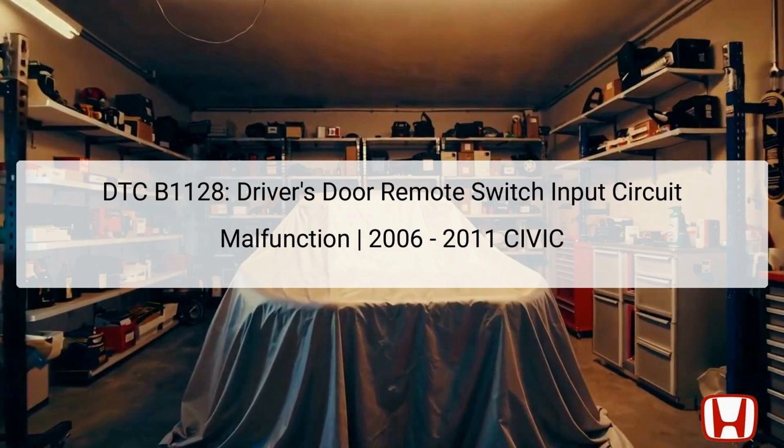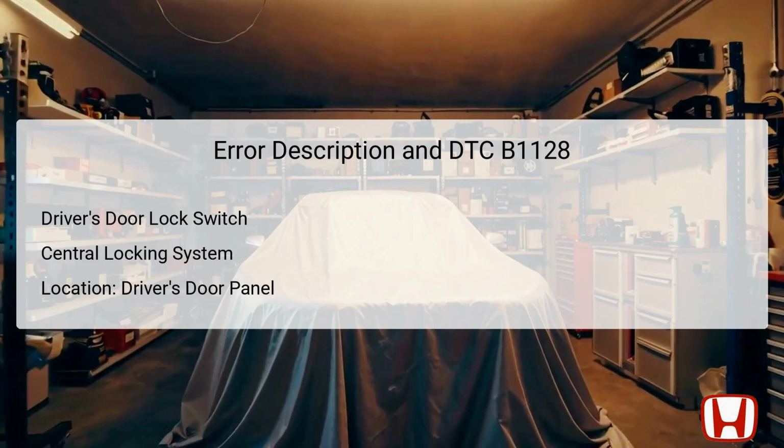The key component affected is the driver's door lock switch, located on the driver's door panel. Its primary role is to send locking and unlocking commands to the vehicle's central locking system. When there's a simultaneous signal detected, it disrupts proper operation, triggering this fault code. It's vital for both safety and ease of access that this switch operates accurately, ensuring secure locking mechanisms and convenient entry. The DTC B1128 indicates a fault in the driver's door remote switch input circuit.